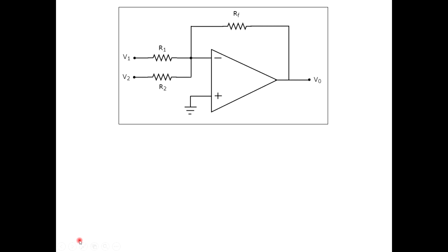So this is a circuit of a summing amplifier. Let's just analyze this circuit. It is very similar to the inverting amplifier with feedback, right? Because the input we are giving is to the inverting terminal. Since we have a summing amplifier, we have to give at least two inputs which can be added. So the two inputs are V1 and V2. If two inputs were not there, we were only calling this R1, and the feedback resistor was RF. There is no input given to the non-inverting terminal. So this configuration is actually an inverting input with the feedback, right?